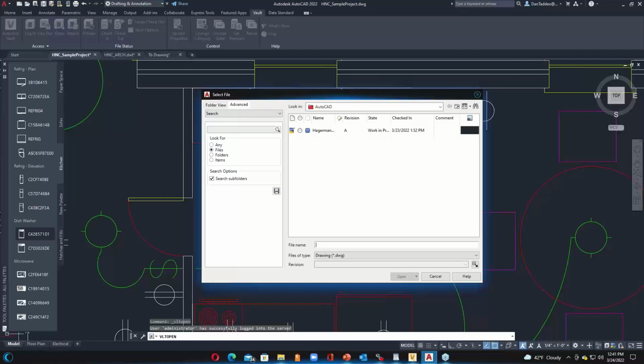Unfortunately, if you get an HP DeskJet 6800, and then next year you get the new version, the 7000 series, even though it's just an upgrade, it'll have different printer heads, and it's not always the same standard. So sometimes those CTB files have to be converted or tweaked based on those plotters. The only way to go through that is printing one line at a time and then comparing those plots and making sure that it matches. But yes, I'll show that in a little bit and what that entails.